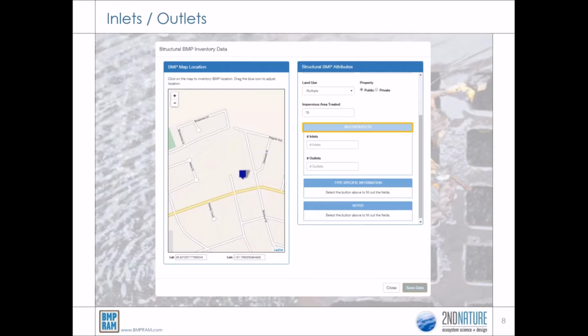If the BMP is old and has not been maintained for a while, you may be required to climb through vegetation or infer that an inlet or outlet may be buried in material. Make sure your designation of the number of inlets and outlets aligns with the type of BMP you are inspecting.